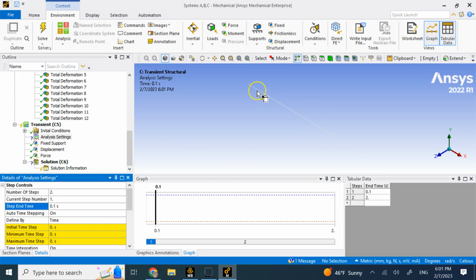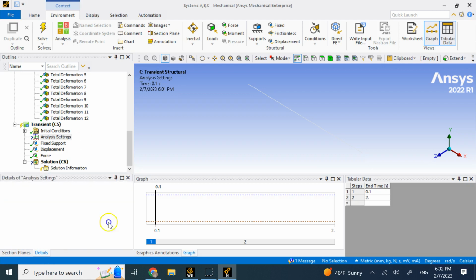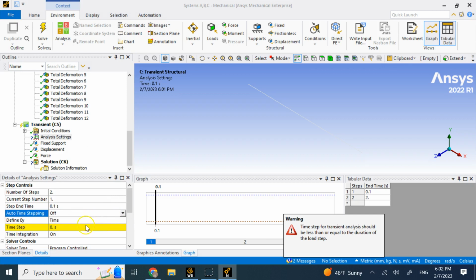Since in this case you're going from a static condition, which is right now, to another static condition, which is the initial condition, you are really not doing anything that is varying with time. You're just setting up the initial condition, right? In other words, your calculations are really static calculations. You are not changing anything with respect to time. You are just setting up the initial conditions. So I really do not need the system to automatically change my time steps, right? I can turn it off.